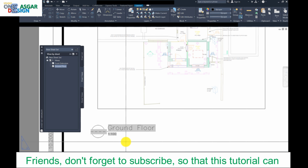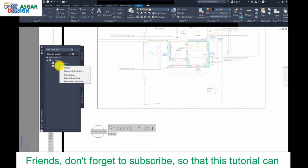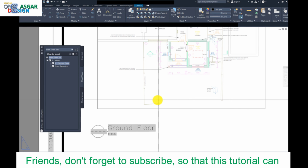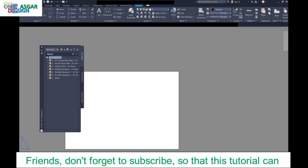So our ground floor label is currently not showing the correct number. So what we need to do is right click the ground floor in the sheet views, go to rename and number. And in here we'll type in the view number. RE to regenerate.